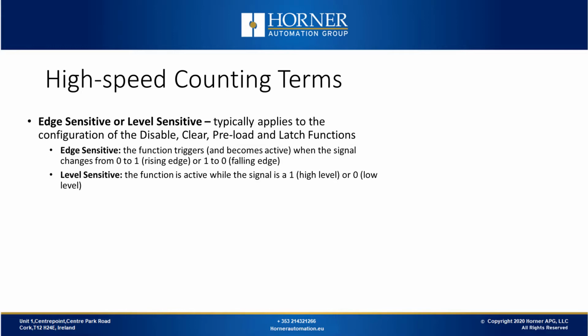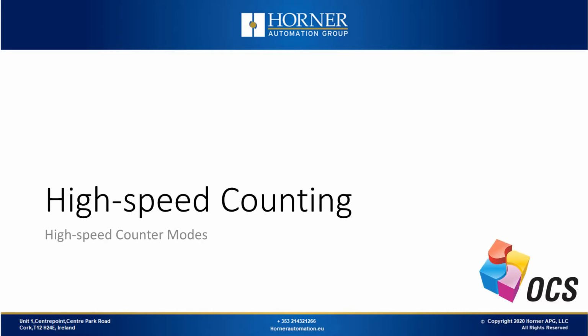Edge-sensitive signals and level-sensitive signals apply to the configuration of the 4 functions I previously mentioned. Edge-sensitive signals trigger when the signal changes from 0 to 1 or from 1 to 0. Level-sensitive signals trigger while the signal is currently at 1 or 0.